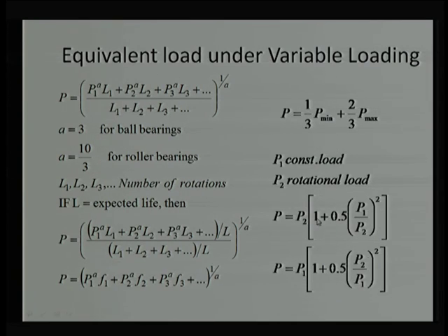So it depends on the magnitude of P1 and P2 and how they compare, and based on that we can find out the equivalent radial load carrying capacity required from a system. Once we know P, we can estimate the bearing life.